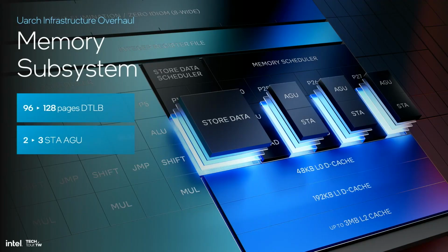In other memory subsystem enhancements, the first level DTLB was increased to support coverage for 128 pages versus 96 previously. And in order to improve load execution in the shadow of older stores, Lion Cove adds a third store address generation unit. It employs a new fine-grained memory disambiguation algorithm to safely avoid conflicts and enhances the store-to-load forwarding scheme to allow a young load to collect and stitch data from any number of older pending resolved stores, as well as from the data cache.